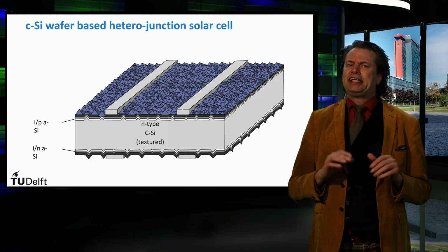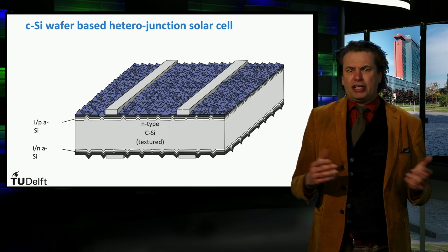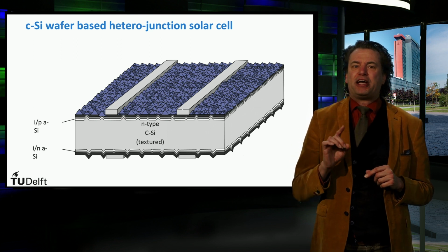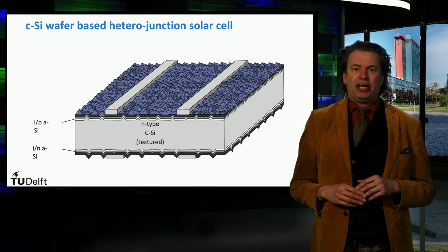The ITO is needed as the conductivity of the p layer is too poor. This results in such small diffusion lengths that the practical metal finger spacing cannot be achieved using the p layers. Therefore, the ITO is used.